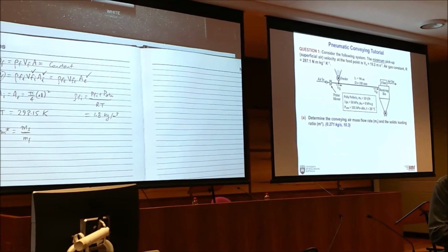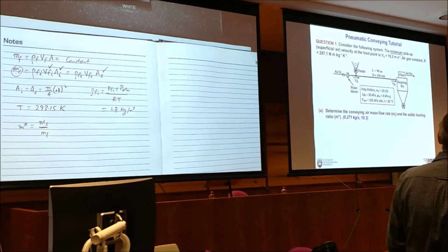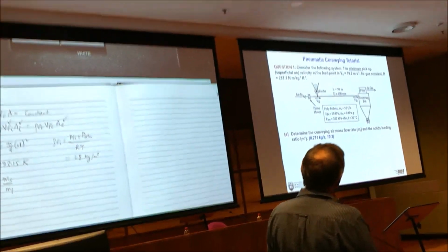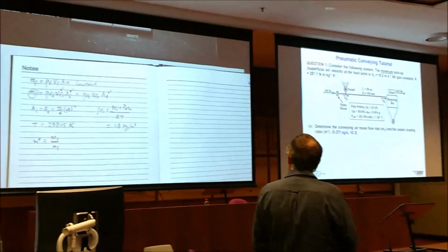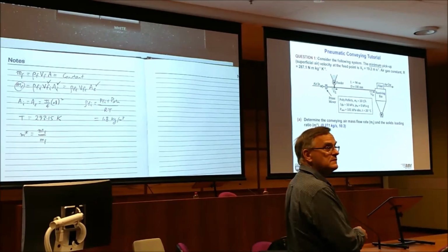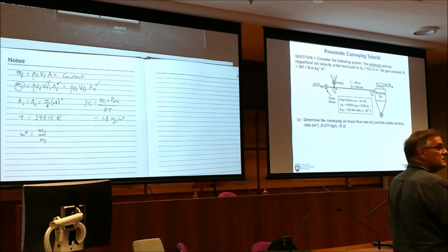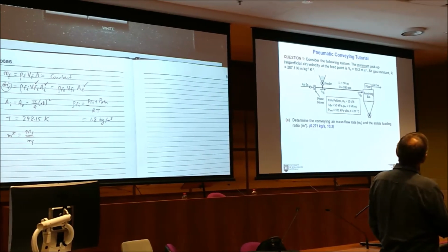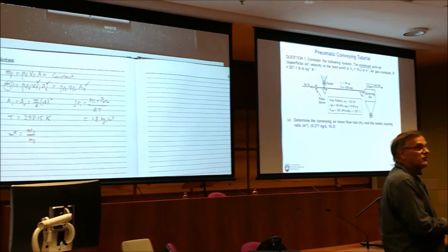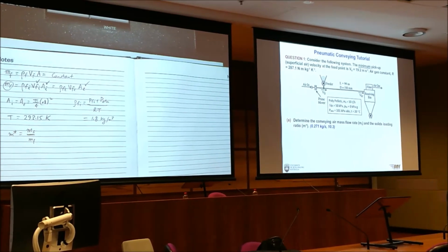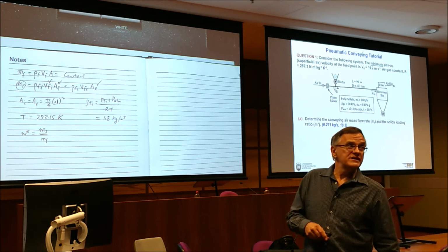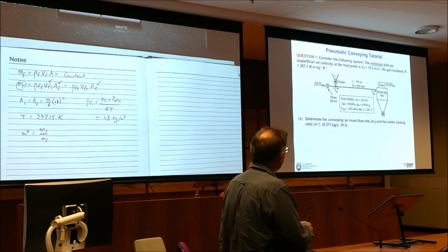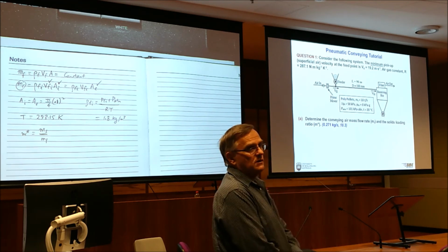So when you say this is the minimum air velocity, that means that airflow is the minimum. That means M star is the maximum. In other words, if we convey more product than 10 tons per hour for the same airflow, we're going to have trouble. Or if we convey the same product flow rate with less air, say an air mass flow rate of 0.25, we're in trouble. We get deposition.